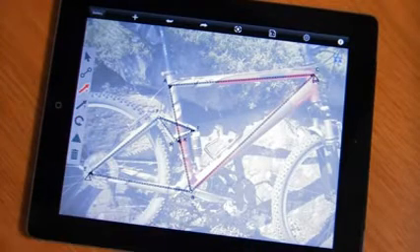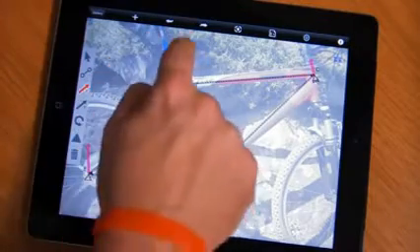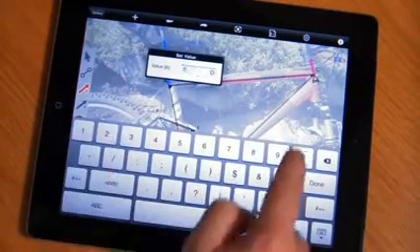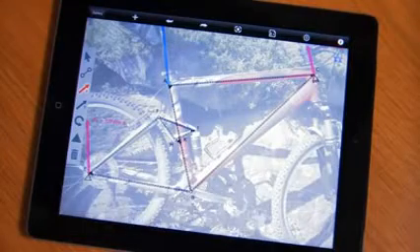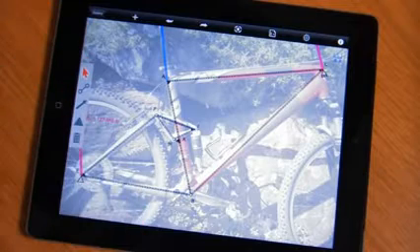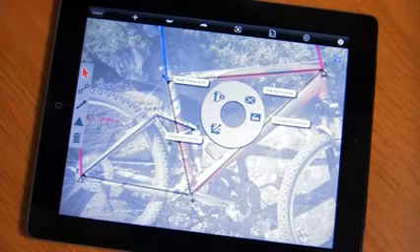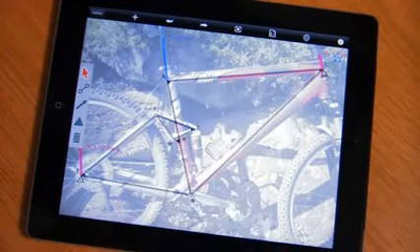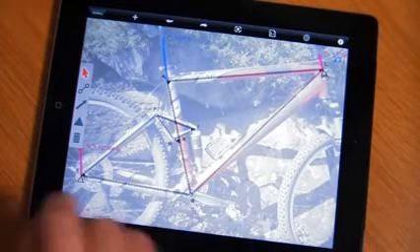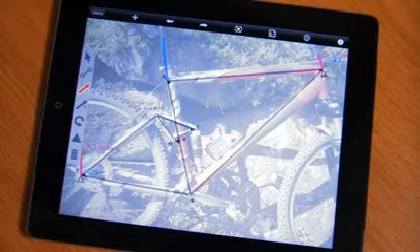Now that we have a solvable problem, we're ready to add our input force. So we'll say that we're going to study for a 200-pound load sitting on the bike. And notice that the force has scaled off the screen. To fix that, you simply go into edit mode, click on the background, and select the scale forces to fit option.